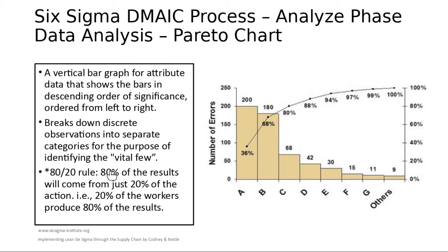So when they apply the Pareto chart and look for causes and analyze the data, they look, for example, here at the first two bars, where the cumulative of 80% of results is found, and that will resolve the problem considering only two factors, which are A and B. So if you focus on only A and B, you are going to solve 80% of the problem.